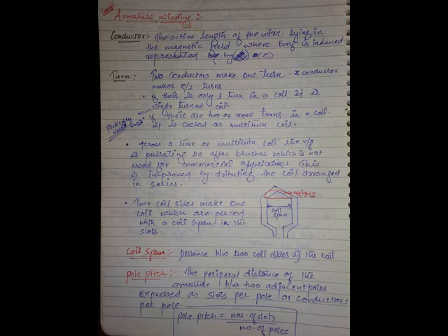So the total armature divided by 4. So even though if there are 6 poles from this point to this point, mechanical degrees are varying, but always under a pole, under the north pole you will get one half cycle. Under the south pole you will get one half cycle. If there are 4 poles, you will get 4 half cycles. If there are 6 poles, you will get 6 half cycles. So one pole is responsible for one half cycle. So one half cycle means electrically it is 180 degrees electrical. So one pole pitch is always 180 degrees electrical. Make a note.